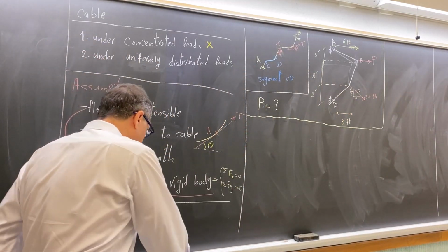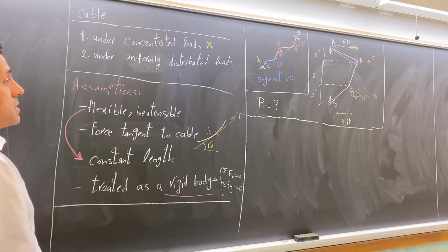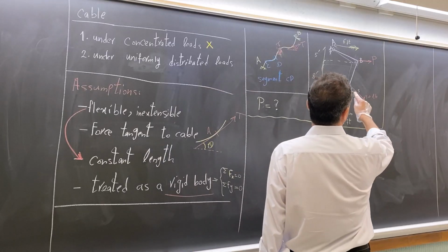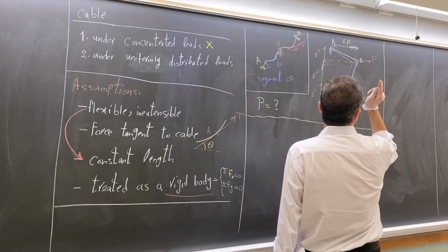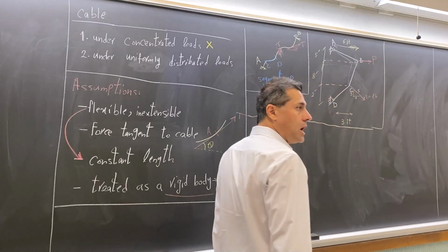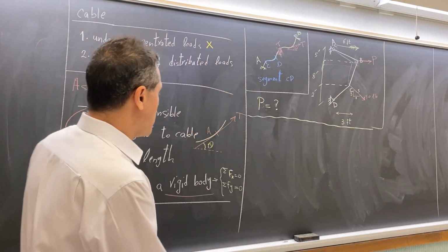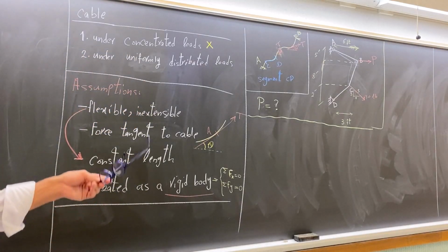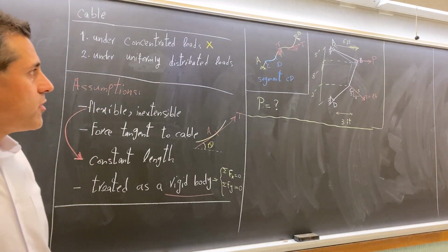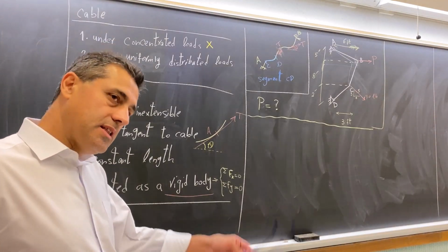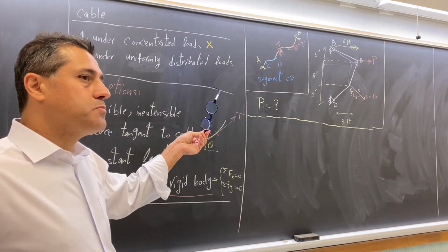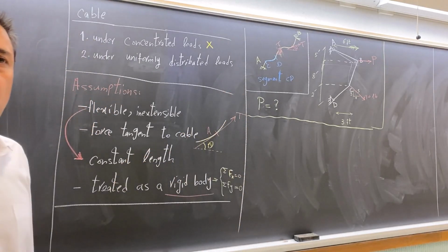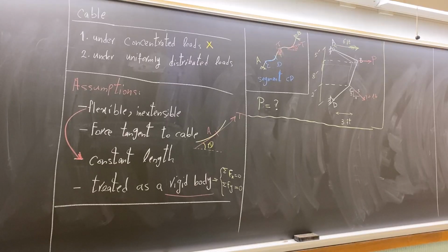These kinds of problems are not difficult. For the solution process, you need to draw a free body diagram for joint C, draw a free body diagram for joint B, and then write sigma Fx, sigma Fy, equations of equilibrium, and then find the unknown. So basically this part is classified under the statics course. I mean, in the past, this chapter was part of the statics course, because it has something to do with equilibrium equations, taking moment, etc.